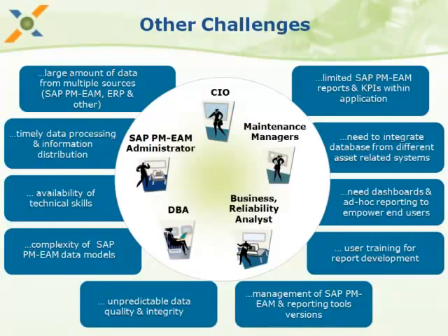Sometimes it is also necessary to integrate SAP with other systems, like your SCADA systems, maybe your criticality analysis systems, or any of these PLC systems where you might gather the meter data, which can help you analyze the corrective work orders against the actual conditions.